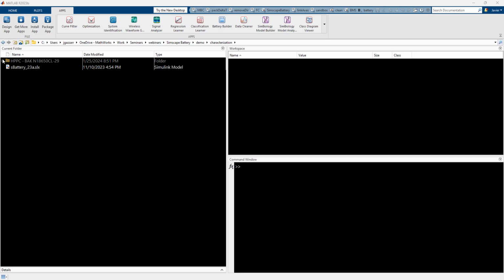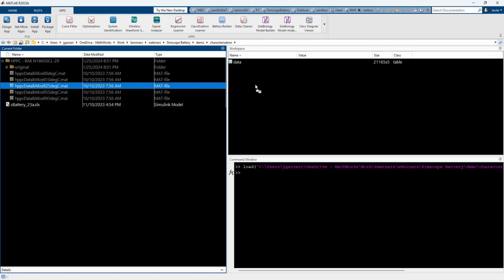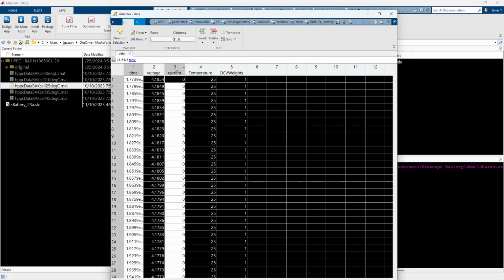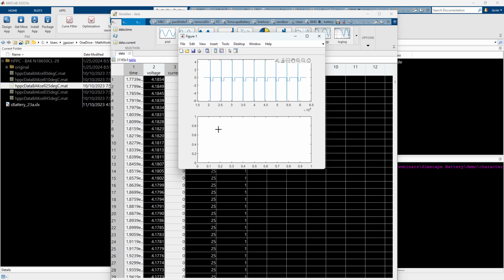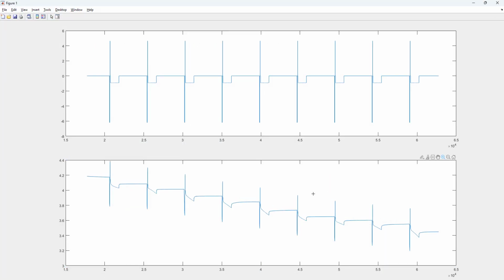Let's see how to do this with an example. These files contain the experimental data corresponding to 5 isothermal HPPC tests. HPPC stands for Hybrid Pulse Power Characterization and is a traditional test for battery fingerprinting. It imposes discharge and charge short pulses throughout the full SOC range with the goal of exposing the battery dynamics response over a range of temperatures. Pulses are very suitable for this because they allow the battery to show its ohmic and diffusional losses directly as the current disappears.